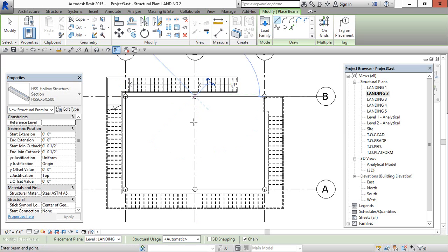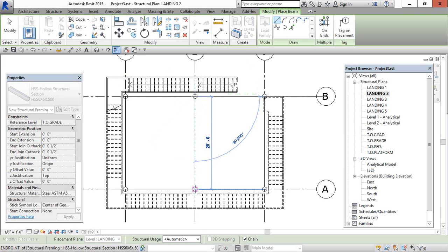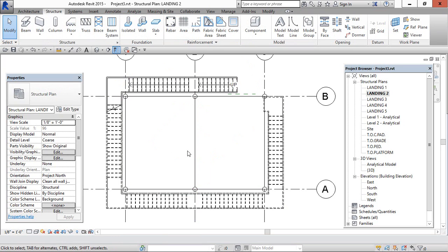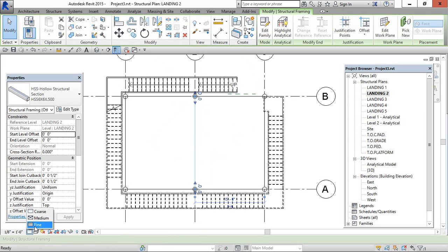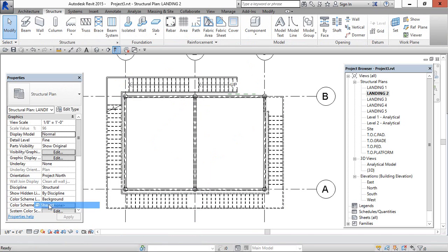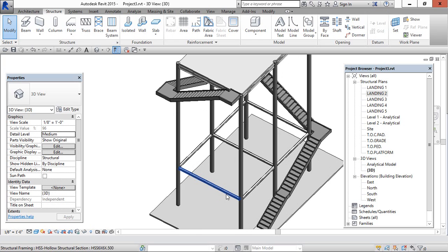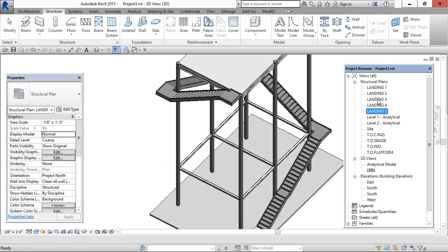There is one more option, beam system, that we can see later. And since this is visible as just a line, we have to change the visibility setting to fine shaded. Now we have created this one, and we need it for another in this 3, 4, 5.